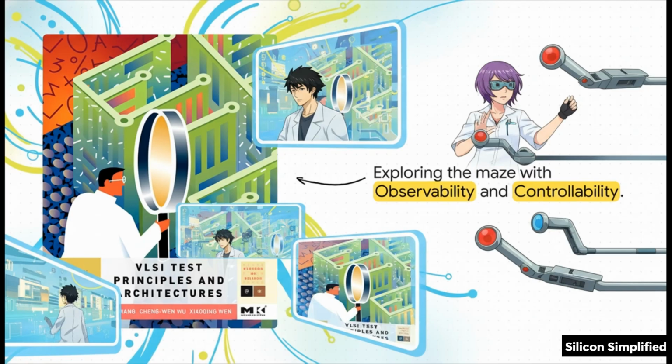First, observability. These are your windows into the maze. It's the ease with which internal logical states can actually be read from the external output pins. Second, controllability. These are your levers. It's how easily you can force specific internal logic nodes into a known state, like a 0 or a 1. DFT is entirely about building those exact windows and levers directly into the maze itself.